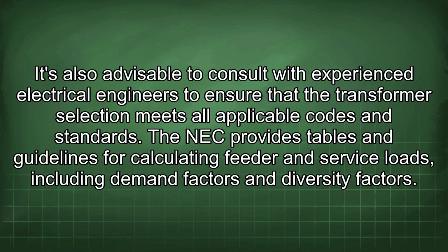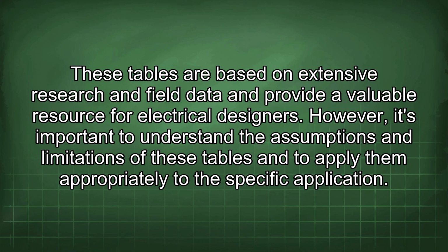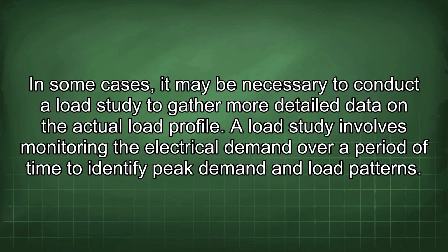The NEC provides tables and guidelines for calculating feeder and service loads, including demand factors and diversity factors. These tables are based on extensive research and field data and provide a valuable resource for electrical designers. However, it's important to understand the assumptions and limitations of these tables and to apply them appropriately to the specific application. In some cases, it may be necessary to conduct a load study to gather more detailed data on the actual load profile.